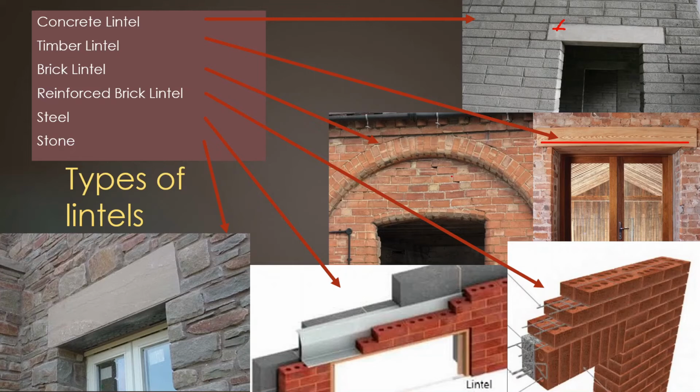Brick lintels. Brick also can be used to support the structure. A brick lintel can act as an arching element. You can see here there is a lintel, and here also some arching elements. Both can carry the load, but they have failed. This lintel is not adequate in shape, or the arching action hasn't worked well. You can see the cracks have formed. Therefore, when you design a lintel for these kinds of situations, you have to analyze it properly. Stress distribution shall be considered.